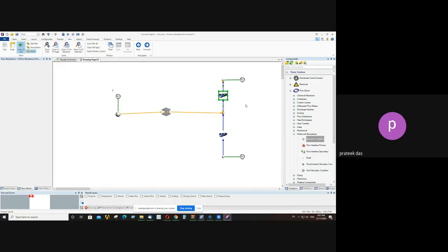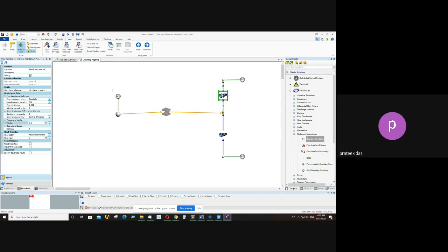So now you can assign the fluid. From the problem statement, 10 kg of water is going to flow within this flow element. In order to assign the fluid, you can select any element like this, but it must be included inside the flow path. So you right click it, you can select any component, and you right click it and go to the assign fluid tab.